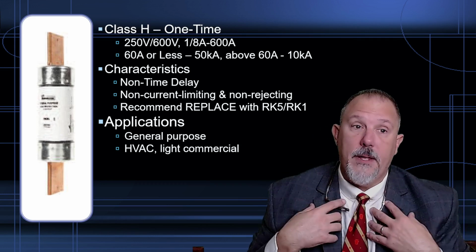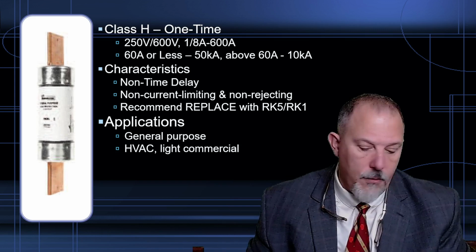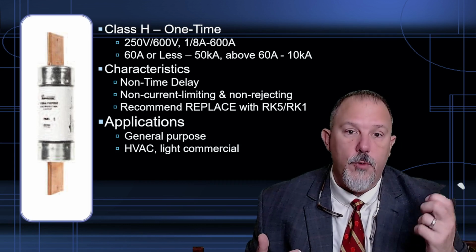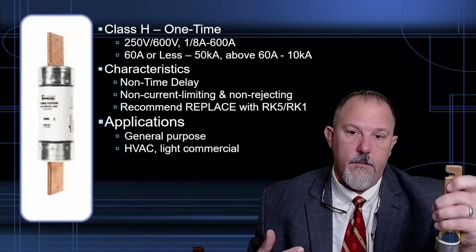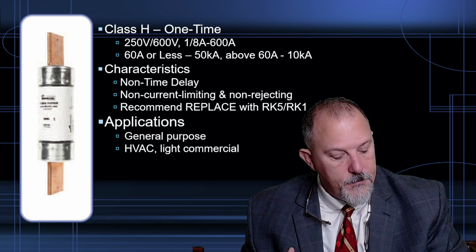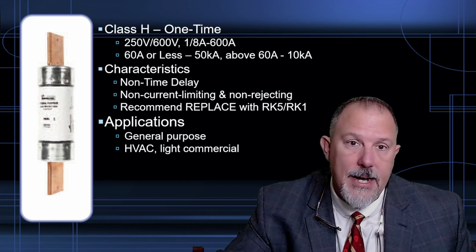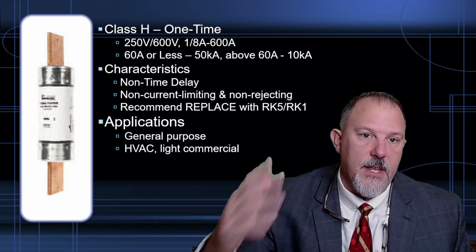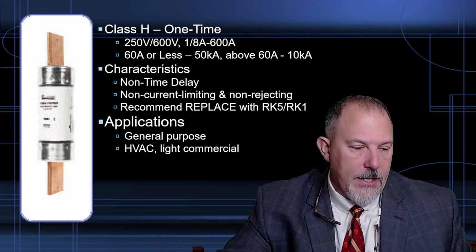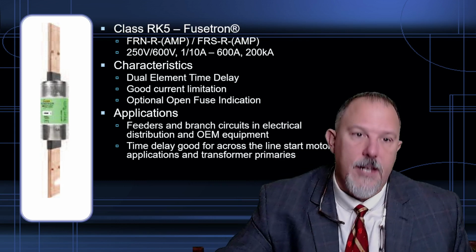Your goal, in my opinion, is to, when you see these Class H fuses, try to get them converted over to a current limiting and fast acting device, which will have the rejection features like that on the blade instead of that on the blade. And the reason is they'll give you better performance, lower incident energy, higher interrupting ratings, the whole bit. That's only 50,000 amp interrupting rating. And then you'll need rejection clips and things of that nature. And we'll talk about those in another session.